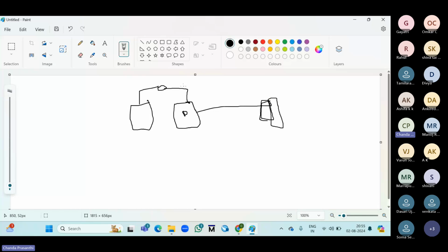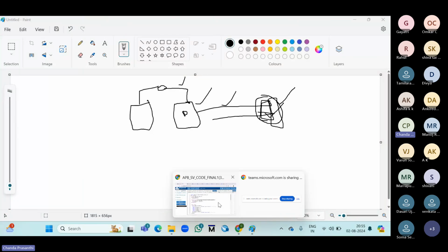So the driver has two connections: one is the mailbox connection, and one is the interface connection. As we don't use the physical interface, since it is static in nature, we use the dynamic interface, I mean the virtual interface. So how will we create that, see here. And also we need to mention the same path. Whatever the DUT signals are, we need to access all the DUT signals using the virtual interface only. Now see how we will write the path.